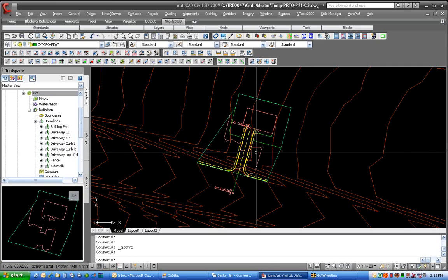All right. It takes a little bit more effort to do this, but I'm finding long run it is easier to debug and fix, because I have had several drawings now from users where their feature lines are corrupted, and through trial and error I was able to get in, find the one that was causing problems, and they caused fatal errors. We were able to delete it. Whereas if you had 800 feature lines all in one break line group, it's very difficult to determine and identify which one is causing the problem.